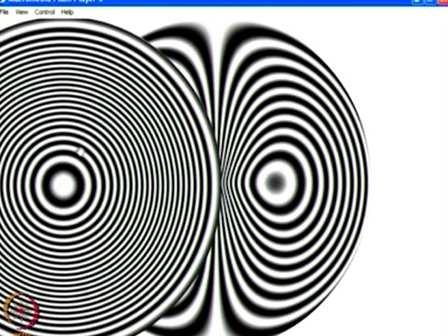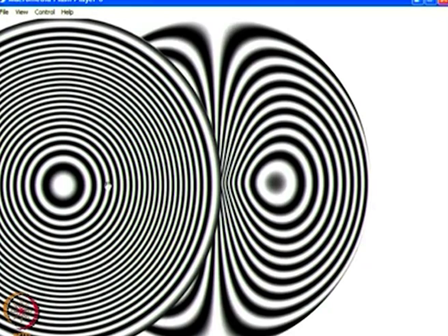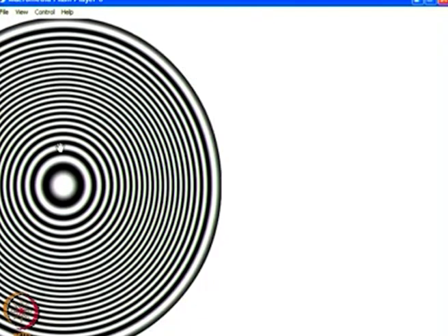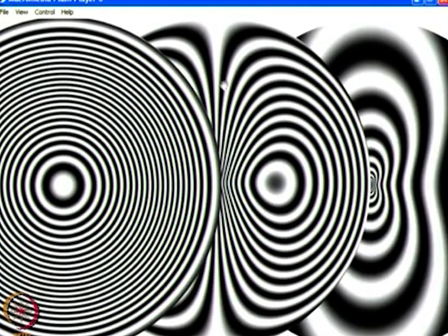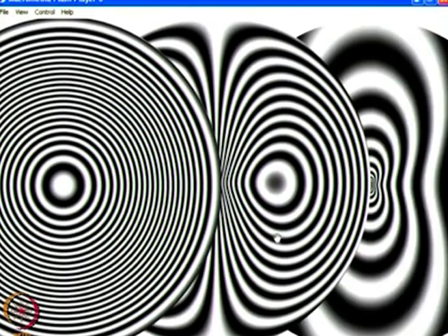Moire. What you see is the simulated fringe patterns, and when you really make an experiment, the fringe patterns will follow this closely, but the quality of the fringes depends on the technique that is being used. And the moment you come here, you see these butterfly fringes, and this you get from shearography.